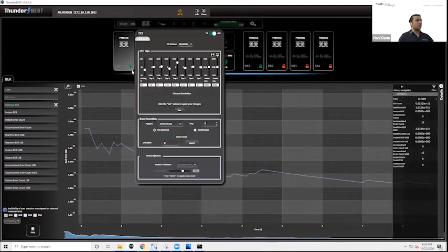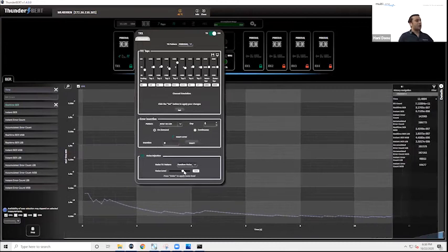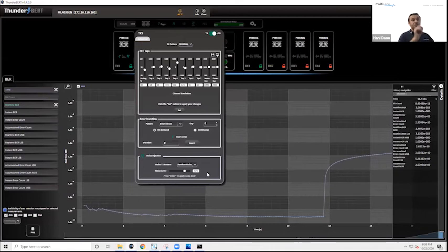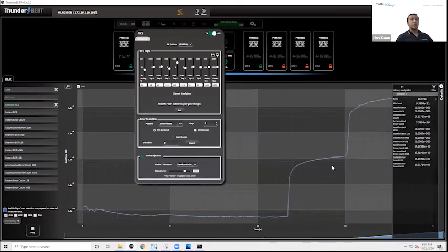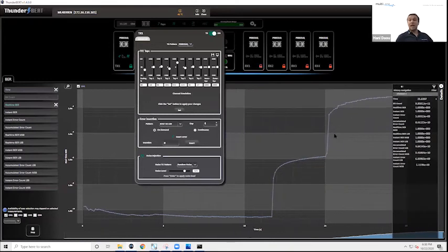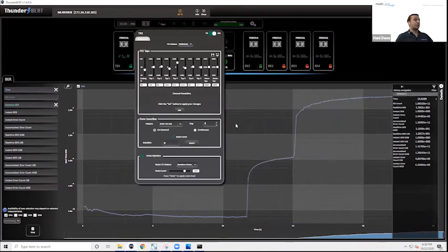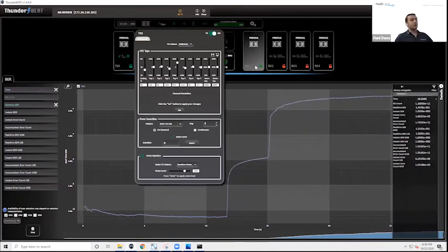Let's see what happens when I inject that noise again. Now I've got noise on the digital scale to be around 500. And you can see every time I crank up that noise dial, we have a boost or a jump in the actual bit error rate. And in fact, now you can actually see the noise is so bad that my receiver is flickering. Now let's take a closer look at that.